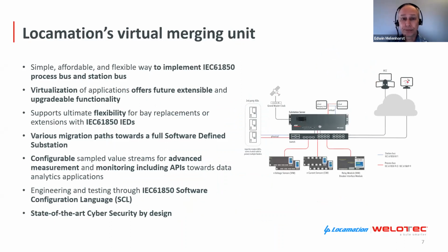So, in short, we have a relatively simple, cost-effective and flexible way to implement IEC 61850 process bus and station bus in existing substations. In the future, the virtualization of substation functions offers extensible and upgradable functionality. It supports ultimate flexibility for bay replacements or extensions with third-party IEC 61850 IEDs. Various migration paths towards a full software-defined substation.